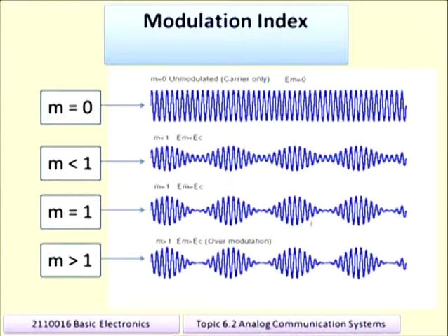These are the amplitude modulation waveforms for different modulation indices. If I stop speaking and am in silent mode, then m is equal to 0 because there is no modulation at all, so our carrier signal remains as it is without any changes. Whenever a person is silent in between while transmitting speech, m is equal to 0.